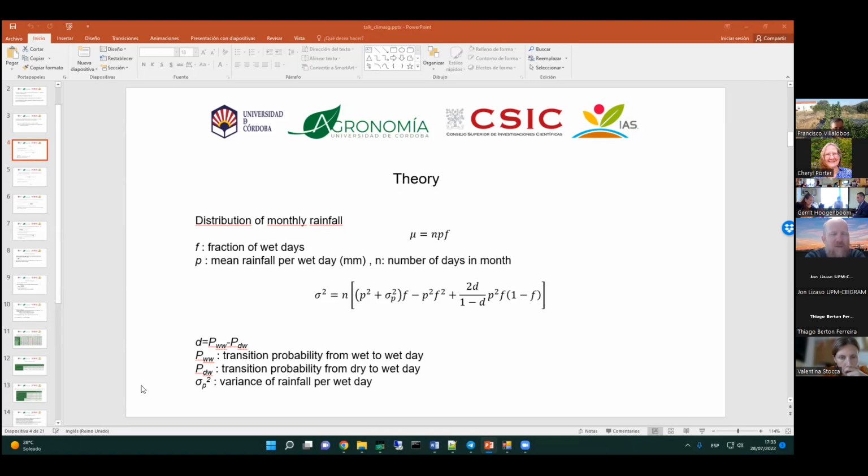Okay. And so it's grass reference. Yeah, sure. For us it's always grass. We don't follow the alfalfa pathway. We don't consider the alfalfa pathway at all. Okay, but in any case, they abandoned the real crop from FAO 56. So grass, now there is no grass at all. ETO is something that doesn't exist, something with a hypothetical canopy resistance of 69 and a hypothetical height of 12 centimeters and so on. Yes. Good, thank you. Sure.